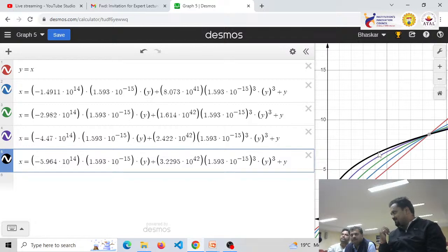Now in the MOSFET, what will happen? Because I have metal, ferroelectric, metal, dielectric and then semiconductor. If I apply some value X onto the gate, the voltage drop across the dielectric will be greater than X. Once it is greater than X, you can get the initial current. So you can assume your NCFET as a normal MOSFET with an amplifier. This is what I was talking about in the morning session: passive voltage amplification using NCFET, using FED heterostructure.